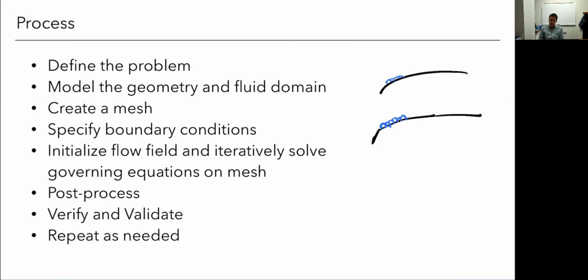But I need to ask myself, what features do I need? If I'm thinking about the full airplane, there are going to be all these probes, pitot probes, for example, and fairings and gaps and all sorts of little geometry things. Do I need all of those? Maybe I can model them in my CAD program, but in my CFD software I've got to mesh all of those, and that's going to make things way more complicated.